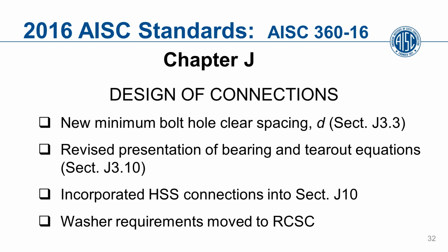Going on in Chapter J, there are new minimum bolt hole clear spacings in Section J3.3, a revised presentation for bearing and tear out equations in Section J3.10, also incorporated HSS connections in Section J10. As I told you, a lot of that stuff was moved from Chapter K into Chapter J. And all the washer requirements were referring to RCSC now. Previously, there were washer requirements in the AISC specification and washer requirements in RCSC. And rather than trying to keep those coordinated, it's easier to just refer to RCSC and use the washer requirements that are in RCSC.